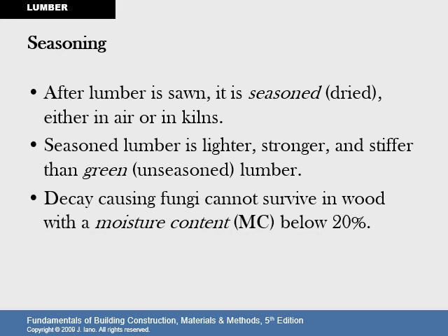Seasoning. How are we going to dry this? After lumber is sawn, it is seasoned, which is dried. It's either in open air or it could be placed into a kiln. Seasoned lumber is lighter, stronger, and stiffer than the green unseasoned lumber. Decay-causing fungi cannot survive in wood with a moisture content, abbreviated as MC, below 20%.